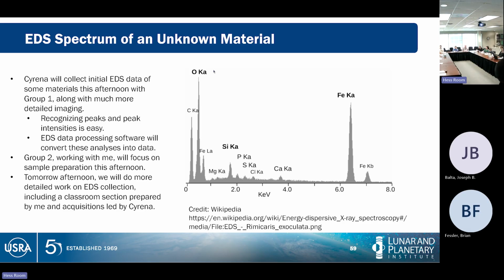This is mostly iron oxide. This is an oxide material, with a little bit of other stuff in it. Recognizing peaks can tell you what a material is made of. Recognizing the intensities on a relative basis can actually identify a material. I can look at this and say, based on the peaks, this is an iron-dominated material, whatever exactly this was that I found in Wikipedia.